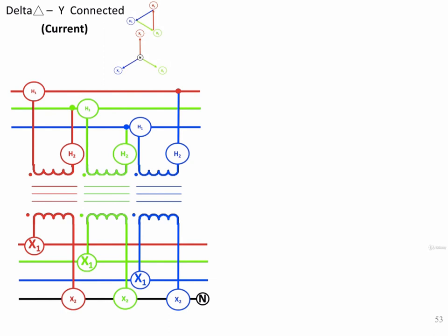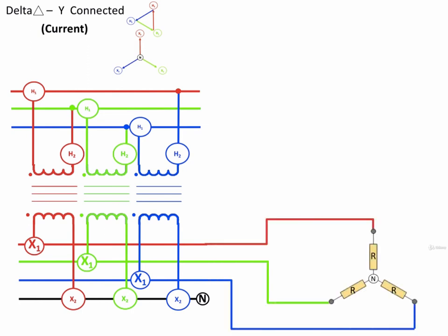And we're going to have to add a load, of course, to make the currents flow in the transformer. As I said, I'm going to add a load to this transformer, and it's going to be connected in a Y configuration. I could have just as well connected it in delta, but we have to choose something, so I chose a Y. And I'm going to maintain a balanced system here. And I'm going to also say that the load is purely resistive because I want to maintain that any phase shifting that's going on is because of the transformer and not the load.